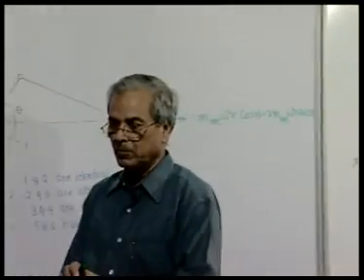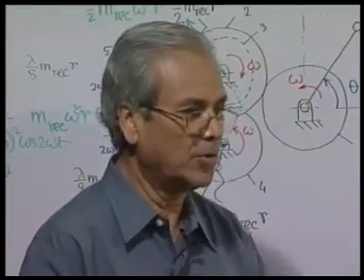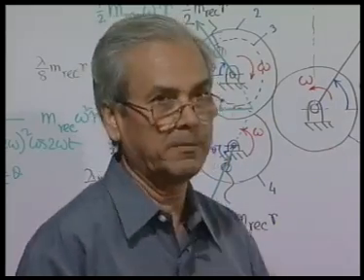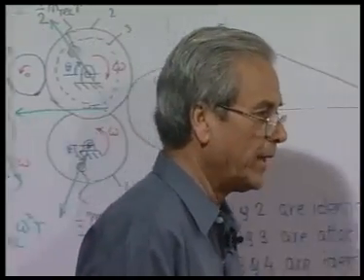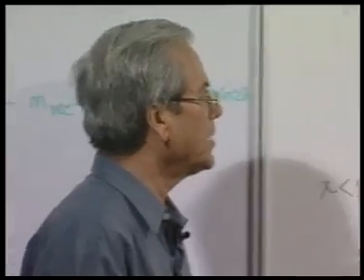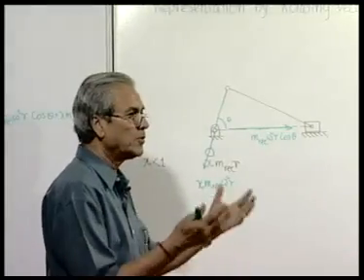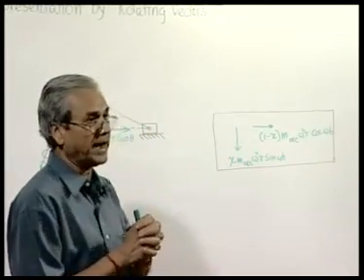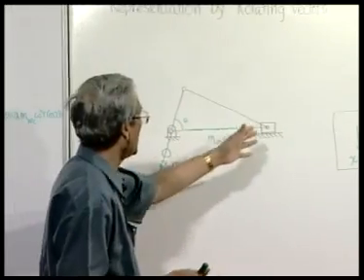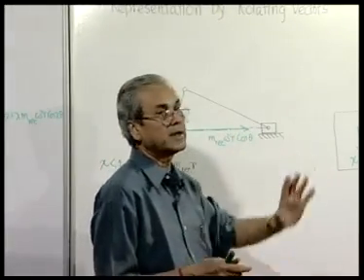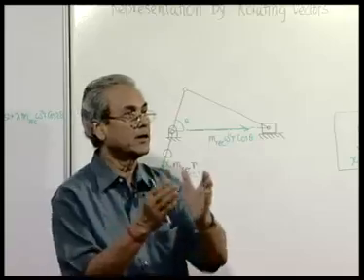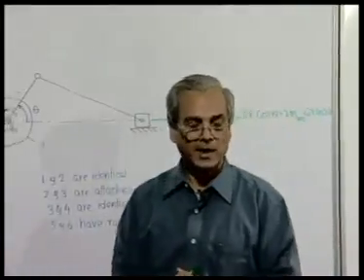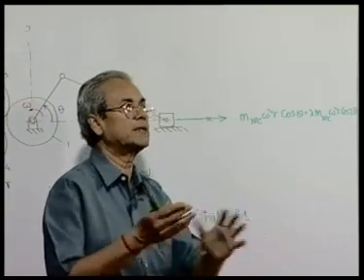Now, the situation is much better, as we know, when a machine is designed keeping its smooth functioning in mind, in such a way that we do not use a single slider system. If we use multiple slider systems, then you can really appreciate the fact that it will be possible for the unbalanced forces generated by the reciprocating masses in the various components of that machine, that means each one composing one single slider system, to neutralize among themselves.